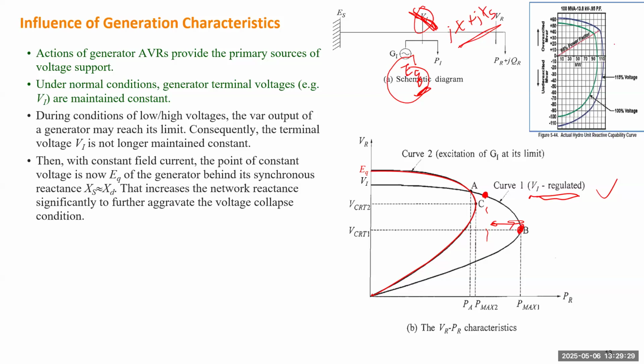So the new PV curve will be this one. So if that switch happens, your operating point will suddenly become unstable because the original PV curve has certain distance to the critical point. But if the system switches to the new PV curve, it's already beyond the limit, so the system can become unstable. So the operator needs to be aware of when such switching can happen.